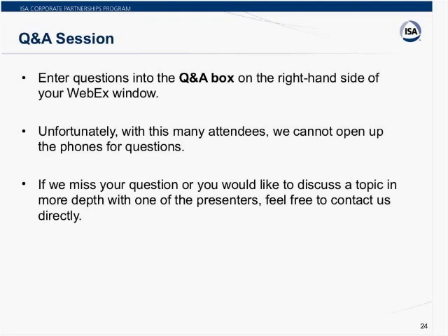Good question. I'll give some high-level principles. I think this question may have come in before Charlie mentioned the 6 to 10%, so I draw attention back to that. And again, that's optimized FEL. Certainly, you could have some FEL efforts outside of that, more on the high side, if you were in a greenfield situation or a large complex migration from manual controls to a DCS where there isn't an existing DCS. You could see front-end loading be 10%-plus because there is no existing system, and the front-end design can be pretty extensive. So again, I would hold to 6 to 10% of total TIC for front-end loading.